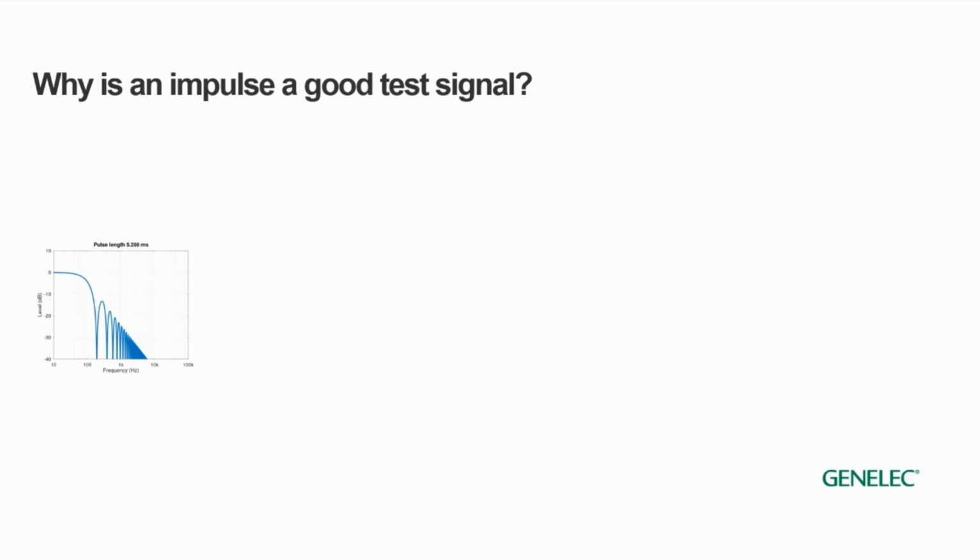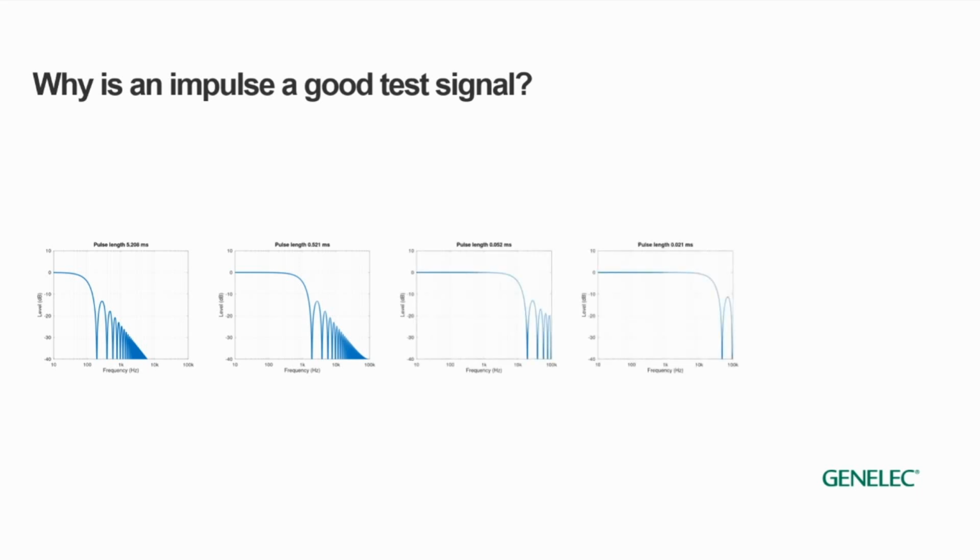So what kind of a clap or impulse would be perfect for acoustic measurements? Let's find out by applying the Fourier transform. Here you can see from left to right pulses that get shorter in time. We start with a 5 millisecond long pulse. It contains plenty of level up to 100 Hz. So this kind of signal would be good enough for subwoofer measurements.